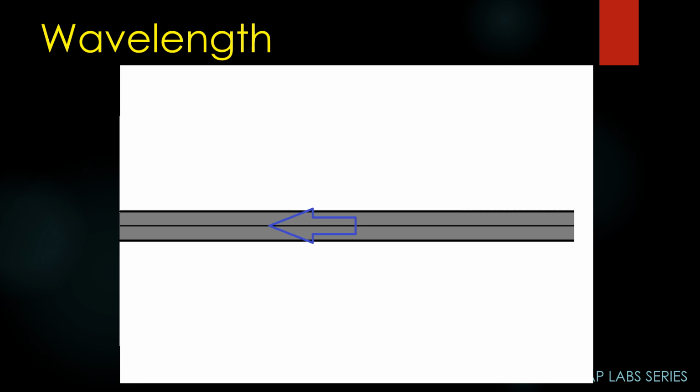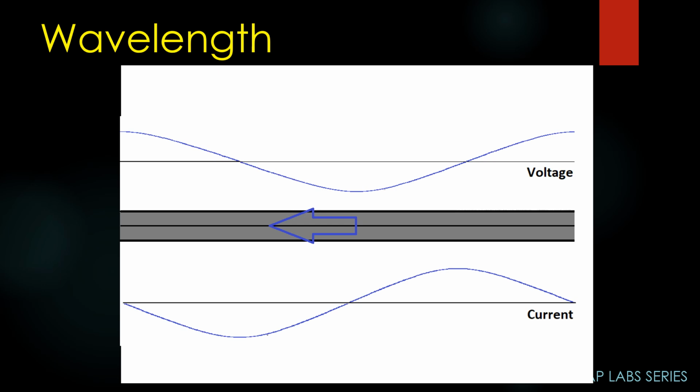Now remember, in a previous episode, I said that the forward power was a traveling wave and the reflected power is a traveling wave. Well, the forward power is a traveling wave here, but the reflected power, in this case, is a traveling wave that doesn't change. What I mean is, at the end, we have an open circuit. So the voltage is going to be high and the current's going to be low, and nothing can change that. So in effect, my reflected power is a standing wave. It just sits there just like you see.